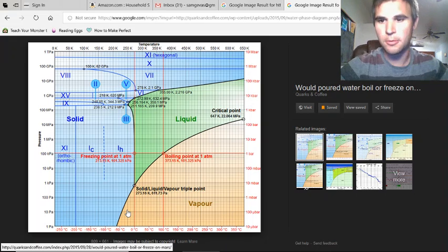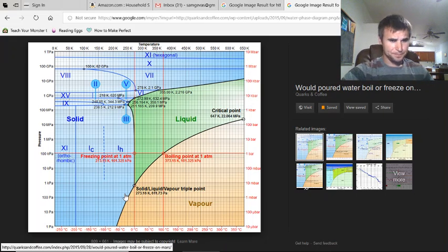They're going to be resistance-based sensors. So you would literally just tell the logic board, check this circuit. If I'm above or below a certain resistance, then pass and go on to the next step. And then it would check for this other one. That would be the pressure check, right? So once it passes the pressure check, then it would check for the temperature. And then as long as it passed the temperature check, then it would go on to the next cycle.